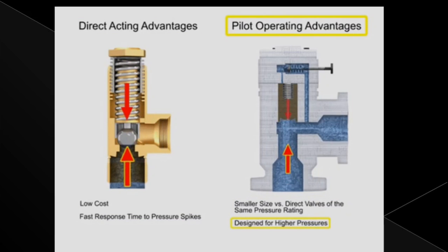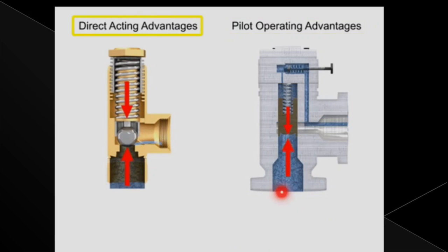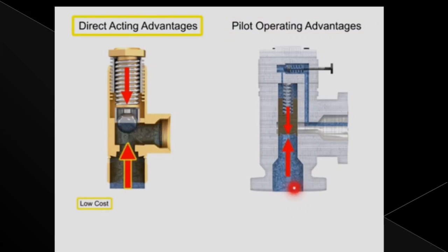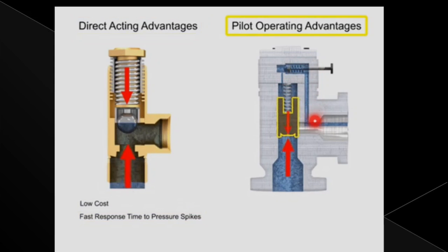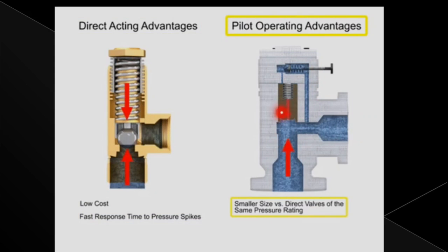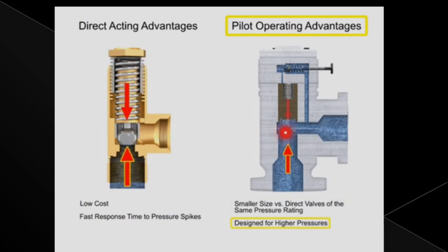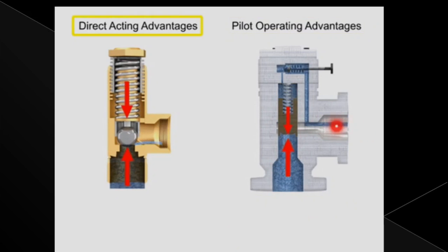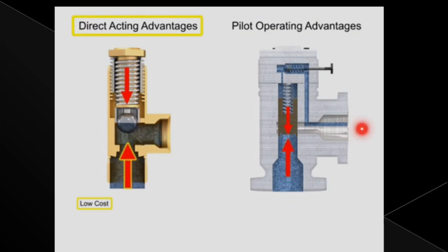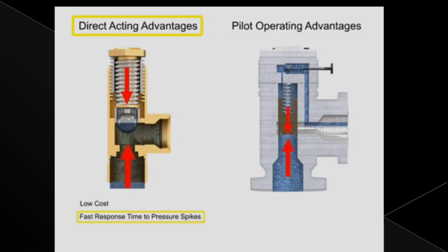First, the liquid is pressurized in here. A small amount of liquid opens the pilot poppet, then liquid flows here. When the pressure increases more, the main poppet also opens and the liquid flows from the main line to the tank. That is how it operates.